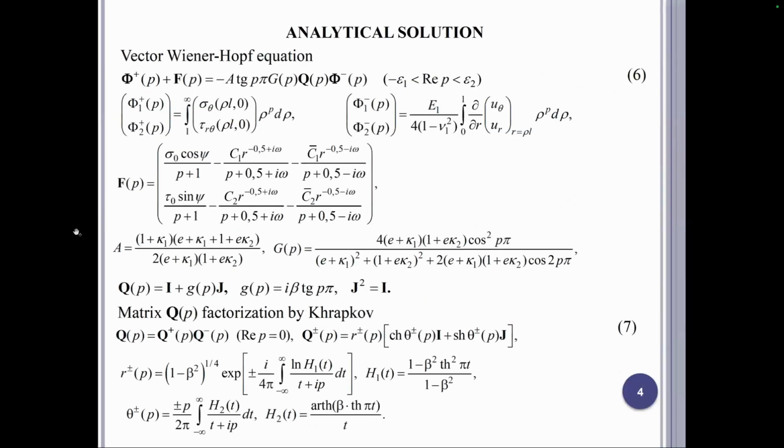Not delving into the details of the analytical process of the solution, we simply cut the process zone and the material along the crack tip, and use the Wiener-Hopf technique with factorization by Gakhov to derive the governing equations, which can be used to determine the process zone parameters.